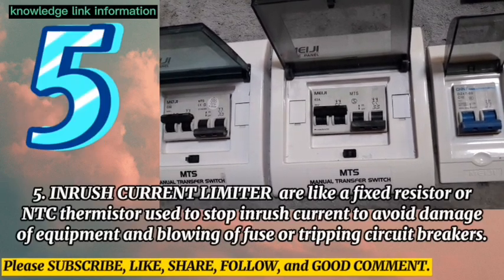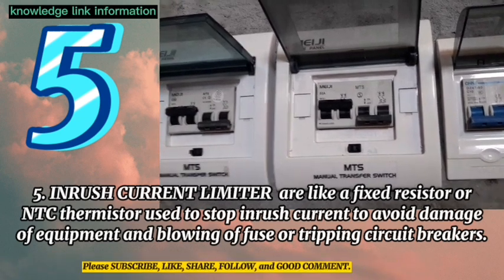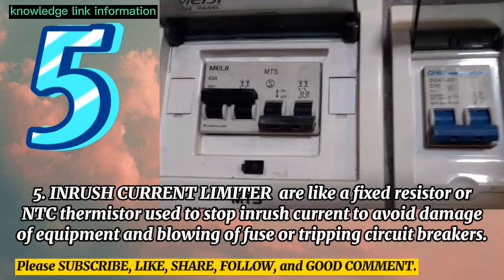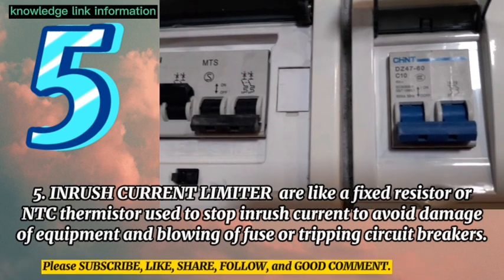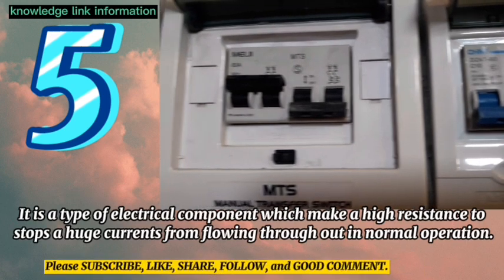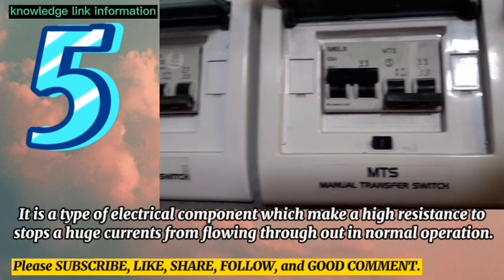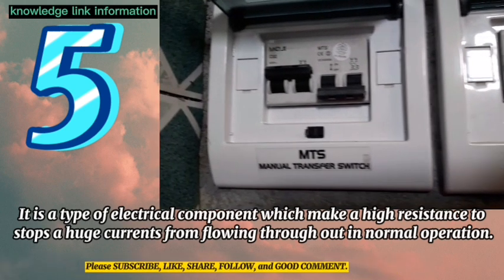Number 5. Inrush current limiter are like a fixed resistor or NTC thermistor used to stop inrush current to avoid damage of equipment and blowing of fuse or tripping circuit breakers. It is a type of electrical component which make a high resistance to stop a huge current from flowing throughout in normal operation.